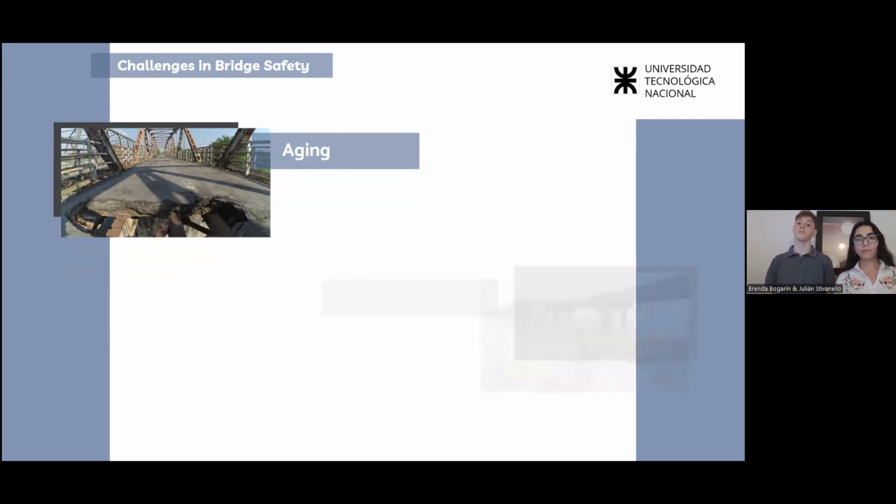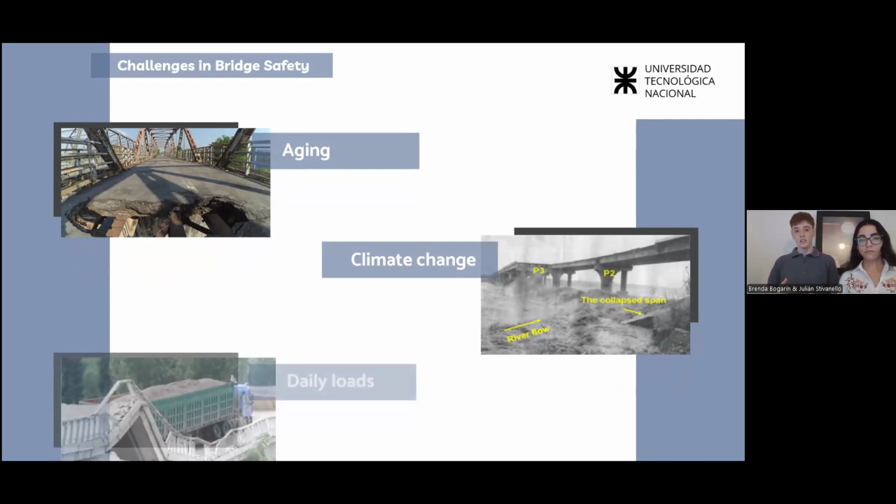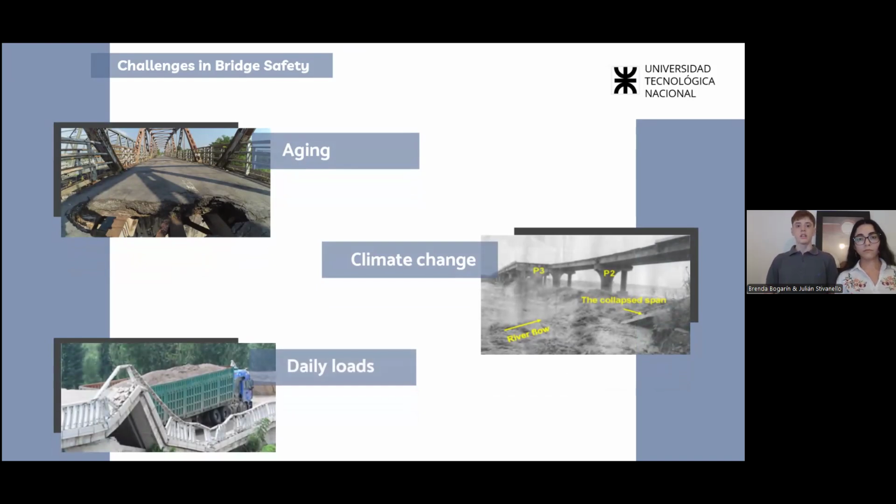Another has to do with climate change. Environmental factors like rising temperatures, extreme weather events, and rising sea levels can affect the materials and the stability of bridges. Another one is the daily loads that the bridges must experience, such as pedestrians, cargo transport, or vehicular traffic. These loads cause the wear and tear of the bridge components, which can lead to fatigue, cracks, or deformations.